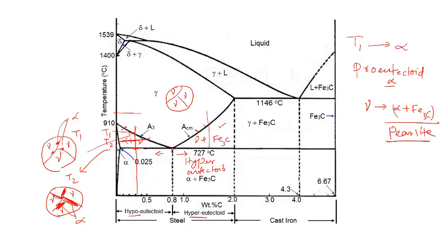Okay, and for the eutectoid composition, what will you see? What will you observe in the final microstructure, and how would the microstructure develop? Yeah, it will be a complete lamellar structure in the final microstructure, because here there is no pro-eutectoid phase. Only the gamma phase is going to transform into a mixture of two phases, ferrite and cementite, which is known as pearlite.